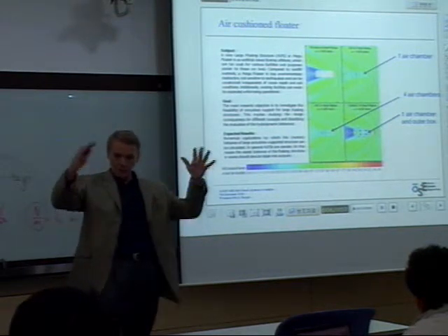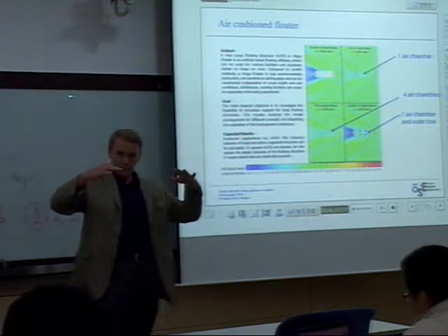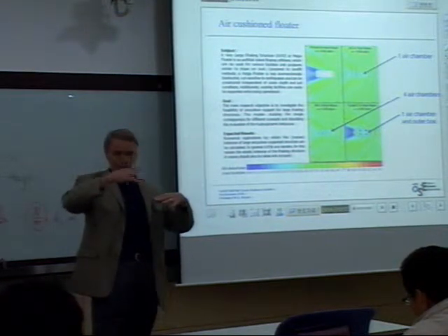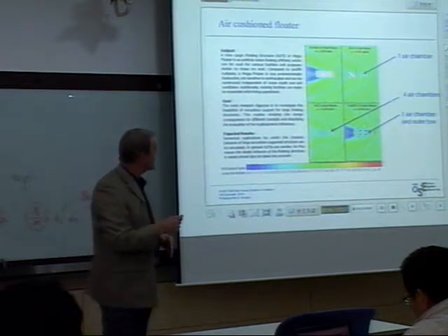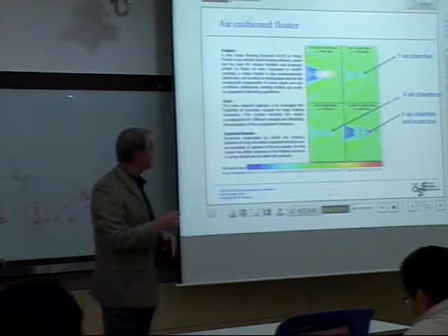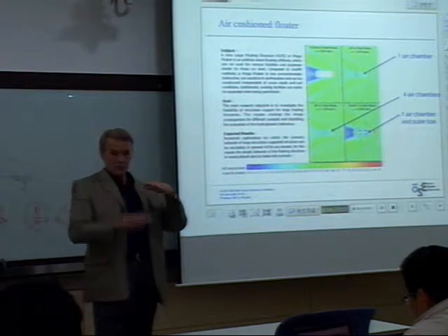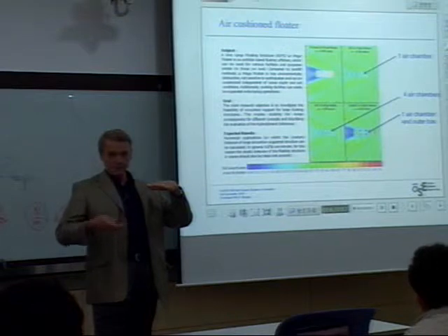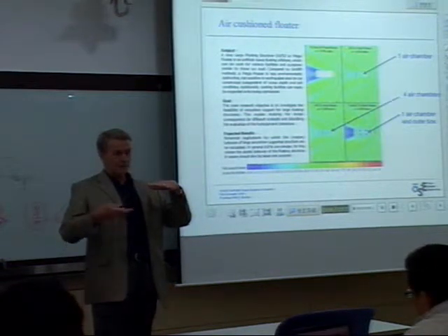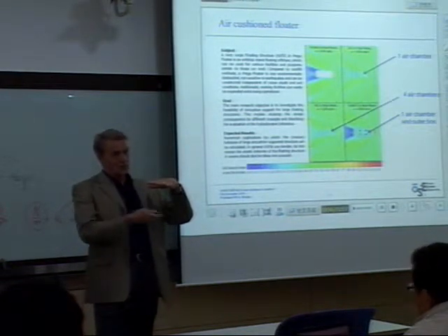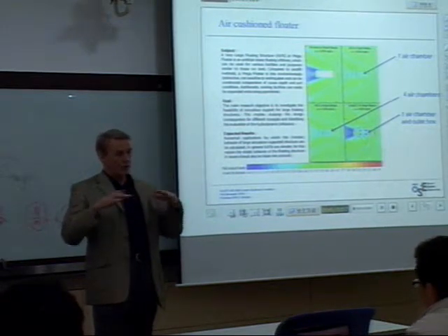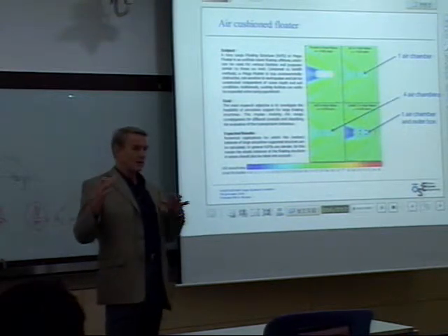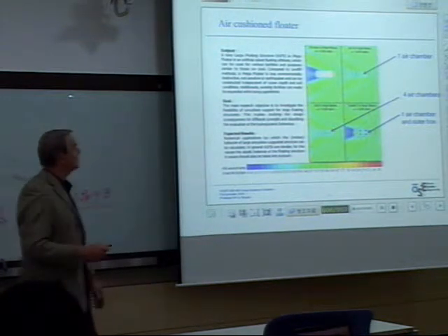And here you see one idea for reducing these pressure forces that you get under this big box. The waves are associated with pressure. Of course, it has to do with the wave height, but in this zone where the structure is, of course you don't have a free surface, but you still have pressure variations under the floating body. That's the same in a ship. You don't have a free surface as such under the ship, but you have large variations in water pressure which are associated with the waves going by the ship.